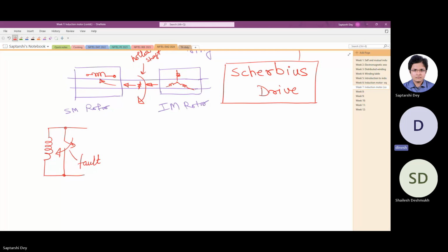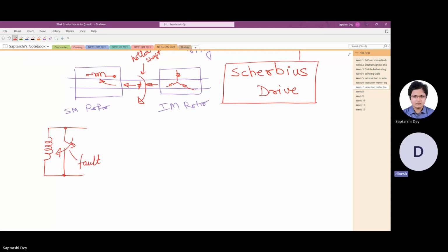The coil cannot withstand it for more than a few seconds after the quench, so I have to ramp it down to zero. I'm connecting a resistor with a very high value, something like 72 milliohm. In 15 seconds it is ramped down to zero. Now I want to use this somewhere. It's just going to waste in the resistor, heating it up.